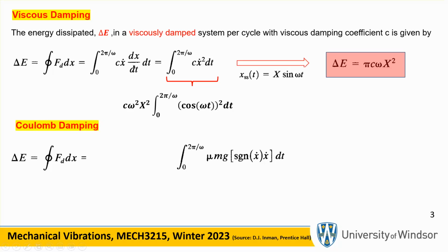So what we do is force the damping force for Coulomb damping. If you go back to your notes from viscous damping, you see that it is proportional to the coefficient of kinematic friction and the weight or the reaction force mg times the direction of the velocity. Okay, now notice that this thing, one, two, three, four terms, actually is your FD in Coulomb damping.